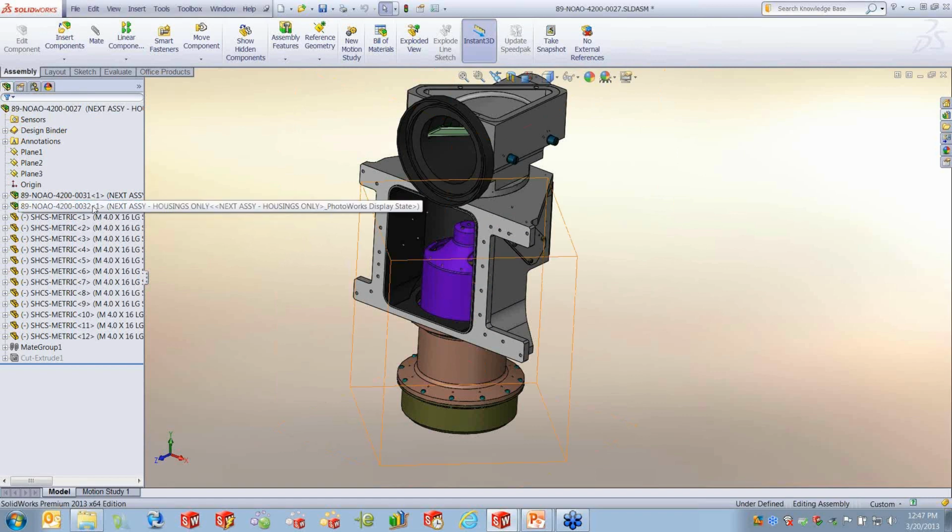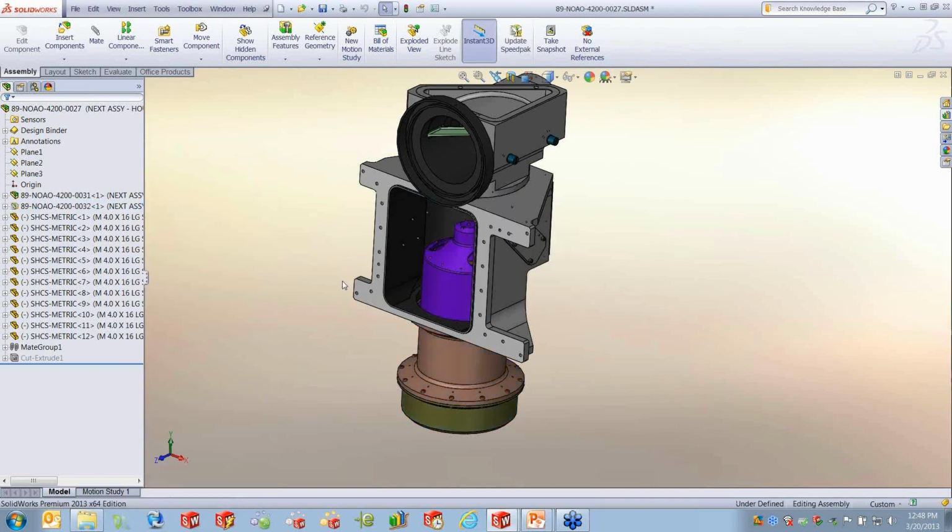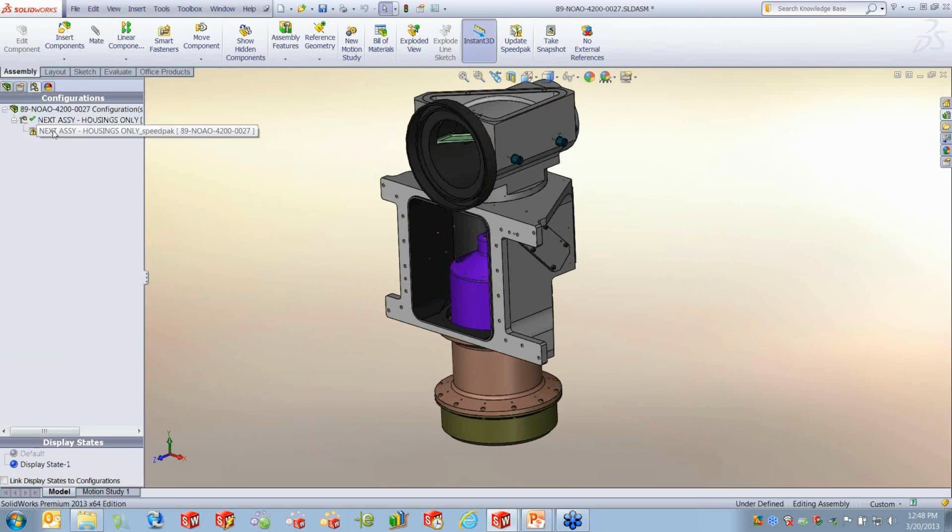You can do this to sub-assemblies as well, even from the upper level. So if I pick on a sub-assembly, I can create a couple different SpeedPacks. One is called a mated SpeedPack, which will only load the faces that are used at this level to mate it up. Or a graphic SpeedPack, which unloads everything and only has the graphical data. You can see that my ghosting is almost eliminated, but I can still see it. So these SpeedPacks are important. Now how do I take this data to the next level?